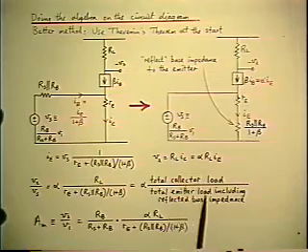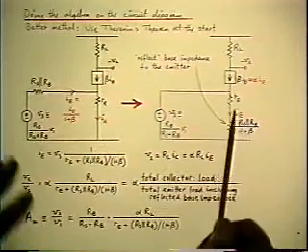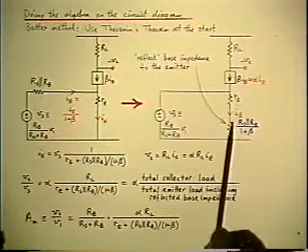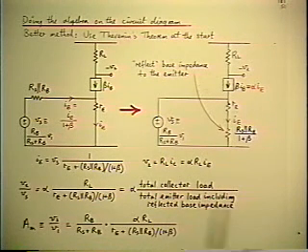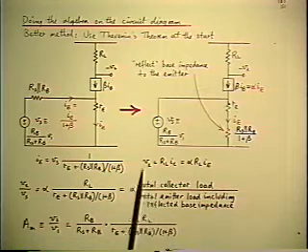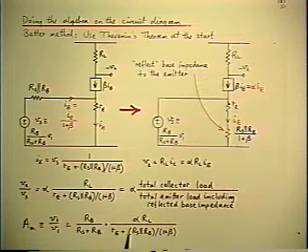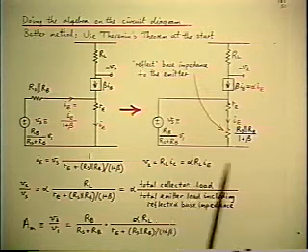So if you just remember that, which is easy to do because it's directly related to how the circuit is working, then you can write this answer down for every common emitter amplifier stage. The derivation is very simple, does not involve simultaneous solution of equations, and the answer is automatically in factored pole-zero form, because that's how it got built.